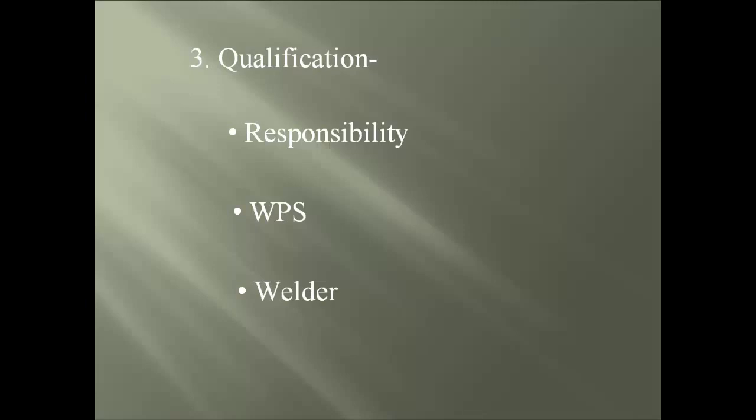Now, if the welder does happen to fail one of these qualification tests, there are 2 cases that are followed. One is the immediate retest, which requires an additional 2 test specimens, or the second case is retest after further training, which requires evidence the training did actually happen.